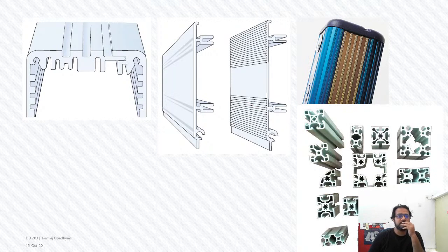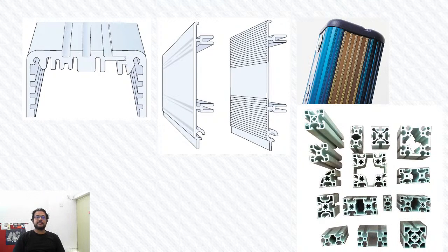I showed you some of these raw materials which are available in the market to purchase. Each one of them is specifically designed as a structural component, but you can use them for any purpose. Along with such extrusions, you get hardware. These channels are designed so that they accept nuts and bolts. You can slide the heads of bolts or nuts inside these channels and tighten. The ability to integrate with hardware has been designed into such extrusions that you get in the market, like these ones.